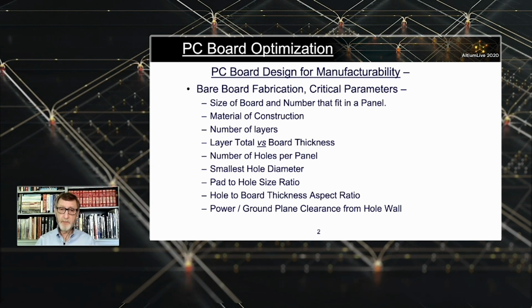That's been a long held belief, because in the early days of circuit board design and fabrication, the materials they started with early on just happened to be a 1/16 of an inch thick. That was simply what they used. There were many reasons for that. Not going to get into that today, but they started with 1/16 material, and the early 1 and 2 layer boards were fabricated on 62 mil thick material. That concept has kind of stuck with everybody.